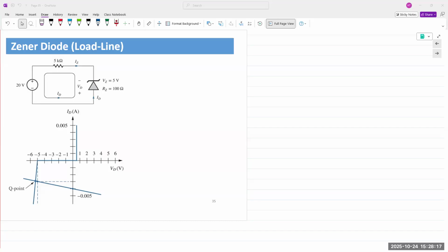The answer is it's made out of silicon. A regular silicon diode behaves like a normal diode in forward bias. So when we did the simulation from -7 to +1 volt, it's a 6 volt Zener diode. So it breaks down at 6 volts. So in the reverse bias, we obtain something like this. And forward bias, we obtain something like this. So regular diode around 0.6 or 0.7 volts.